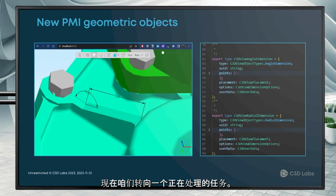Now let's move to the tasks we are working on now. One of them is measurements. At the moment, we have implemented graphical objects for measurement, such as linear, angular, and radial dimensions. The TypeScript API already had the ability to create these objects. Now we have processes to create such dimensions specifying the points, but they are more for debugging.